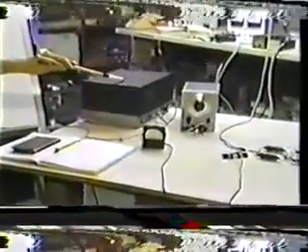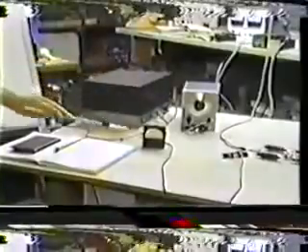Now we have a probe for detecting magnetism, and we have a probe for detecting dielectricity. Coming to the workbench here, we have our audio oscillator. We have our power amplifier, which basically constitutes our generator. Our magnetic detector consists of a thermomilliamp meter that has a small filament in it that gets hot when current flows through it, and then the temperature of this is measured with the thermocouple and produces a scale on the meter.